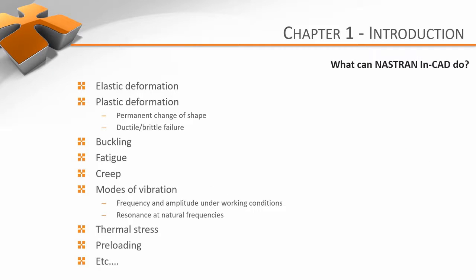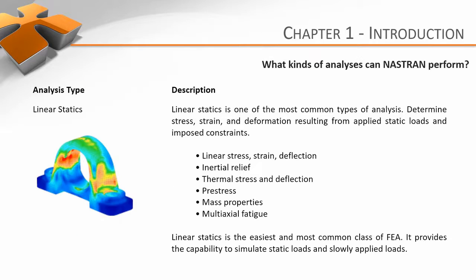So by this point, I've banged on and on about how good Nastran is, but what can it do exactly? Good question! Like all the other FEA programs out there, Nastran's all about setting up and running simulations. Basically, grabbing your designs and putting them into situations that you're interested in. Typically, you'd want to know what load your design can take, or how it will deflect under ordinary or extraordinary conditions. Perhaps you'd like to know when it'll start to vibrate, or whether it's as optimized as it could be. Nastran offers a whole bunch of analysis study types that can tell you exactly these things. Whether it's linear, non-linear, fatigue, there's an analysis type for it.